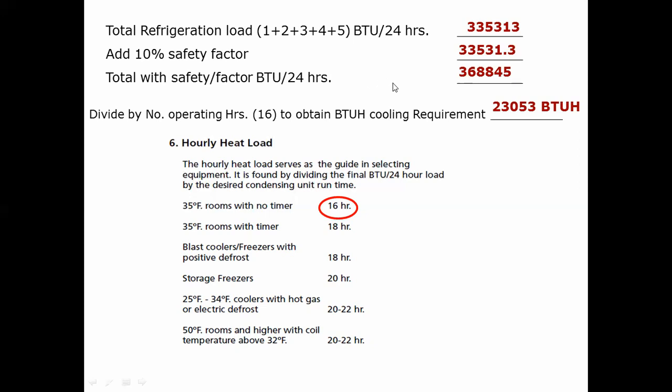Okay, fine. So this is our BTU per hour. Do one more thing. Just convert this BTU per hour to ton. You know, one ton is equal to how much BTU, you know it. So kindly find out how much ton capacity this is, and find out the answer also.